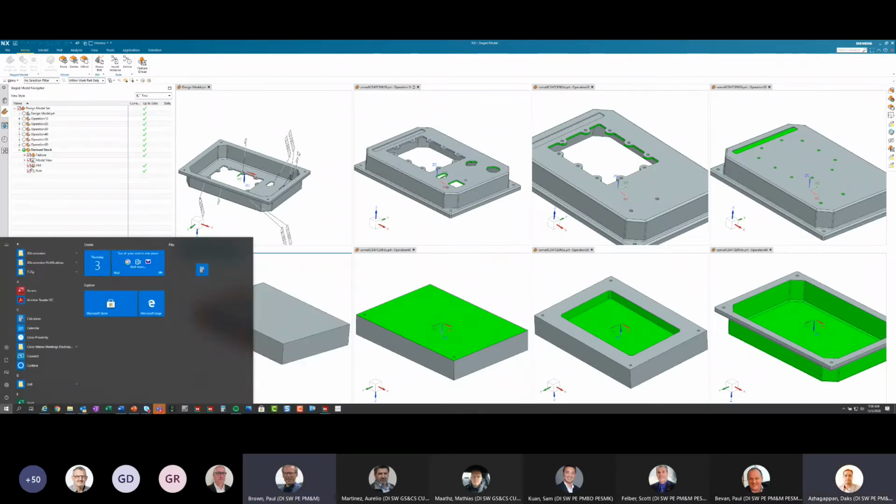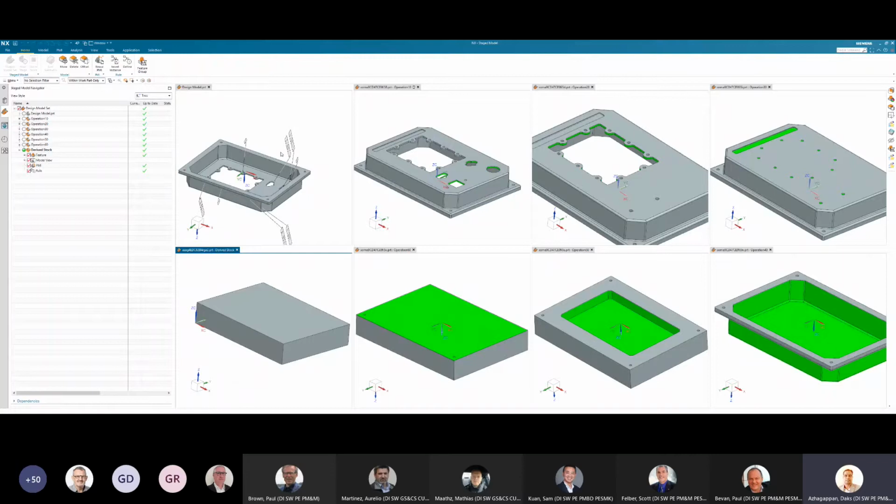All right. So in this one, I wanted to show a couple of things to demonstrate the top-down approach to get to the derived stock. I think I was on the derived stock function. Right now, the function I used was taking the reference from the product data. I've seen customers having all those stock information already in a database in Teamcenter. So instead of going through the derived stock approach, you can also go into the library, bring in the necessary stock you need for this particular part, and adjust the sizes if you need.